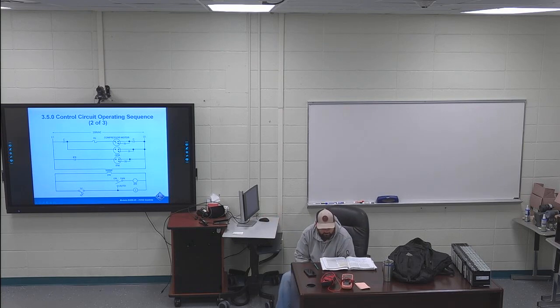But it talks about that in the bullet points where it's going through those 4 bullet points. My highlight is the third bullet point, first sentence. The outdoor fan motor, OFM, runs whenever the compressor is on. That is, if that compressor is running, that outside fan motor is running. The next paragraph after the bullet points, I have the whole thing marked to read through, and then I keyed in on the second to last sentence. So I'm going to read through the whole thing and then key in on the second to last sentence.